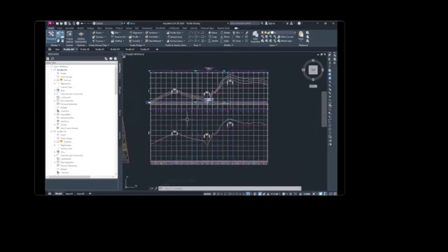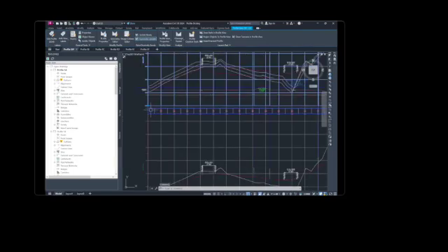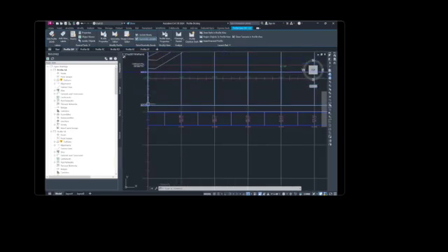Zoom out so you can see both profile views. When you apply the major grid style, which includes grid padding above and below the profile, PV1 enlarges to overlap PV2. Click PV2 and move it up above the title block for PV1.